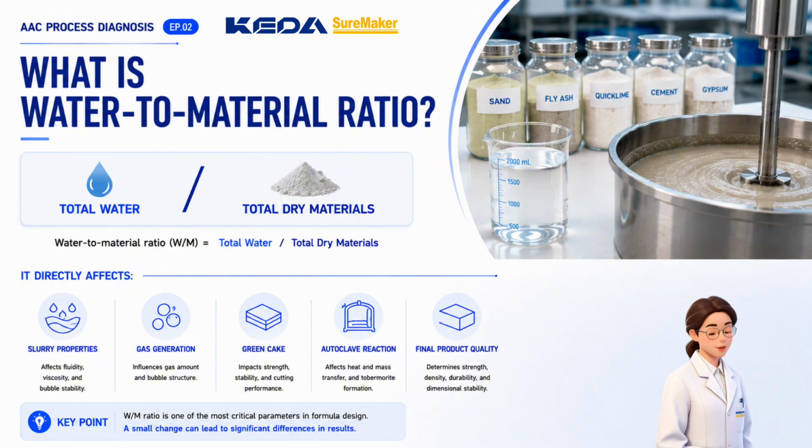Now, let's look at the water-to-material ratio. In simple terms, the water-to-material ratio refers to the ratio between the total water and the total dry materials in the slurry system. The water includes water in the original slurry, water in the recycled slurry, additional water added during casting, and water brought in during aluminum paste premixing. The water introduced through aluminum paste premixing is often negligible in formula calculation. However, the water used to prepare aluminum paste slurry at a certain ratio still needs to be included.